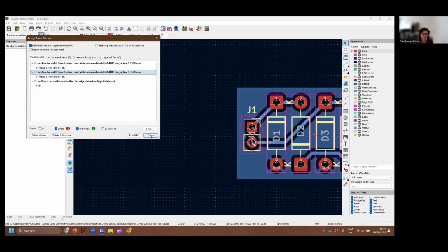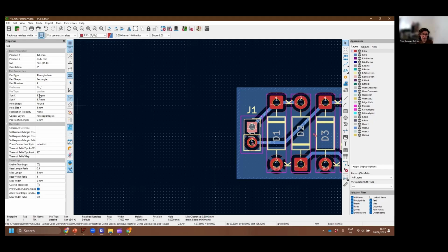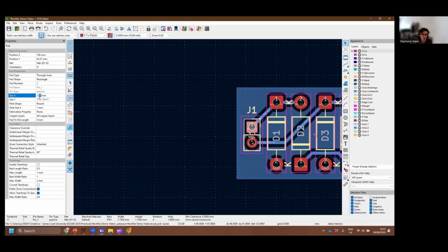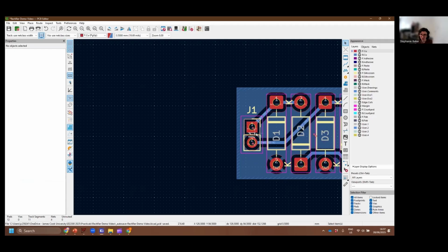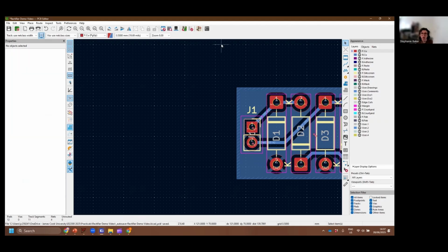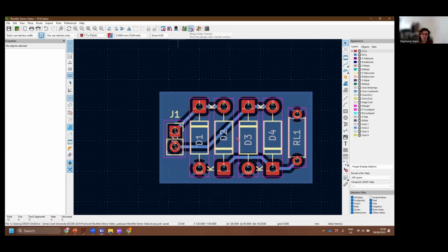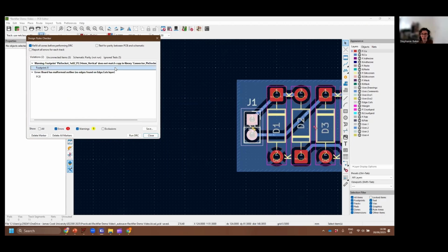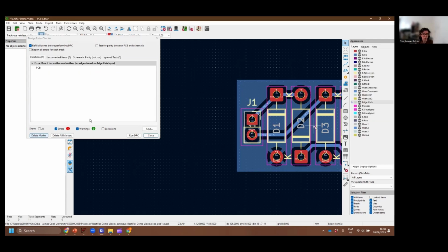So what I'm going to do is close this and select these pins, and I can actually just change the X and Y dimensions here. We were only 0.5 mil off, so I'll go up to 1.8, that way we're giving ourselves a little bit more clearance on both the X and Y dimension, given we've got a round hole and a square outline. And then I'm going to repeat the same thing for our round pad, so I'm just going to go up to 1.8. Now if I rerun our design rules checker, hopefully that's enough clearance for it to be happy with life. It does now give a warning that we've modified the footprint, but that's okay. We can ignore that particular warning.